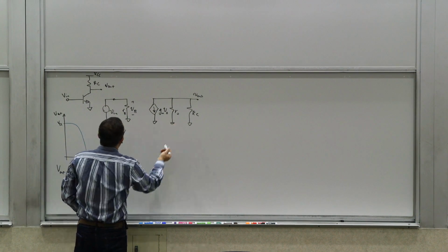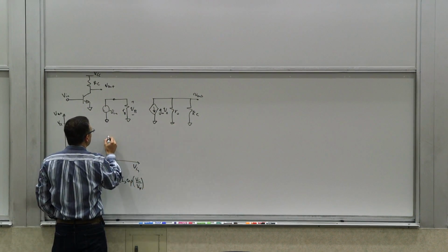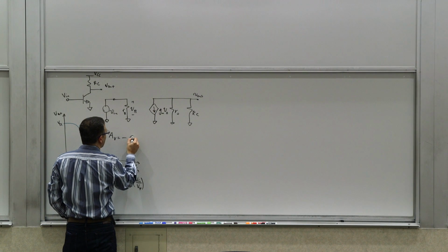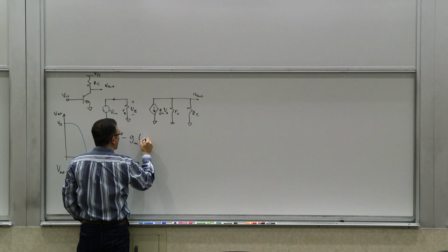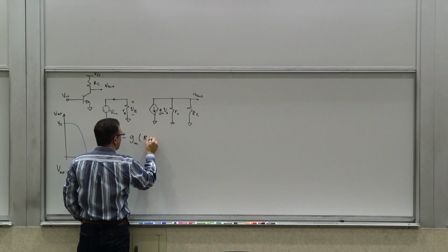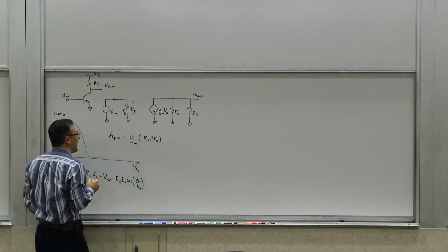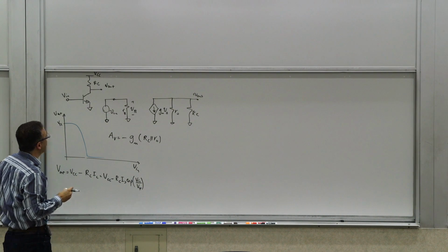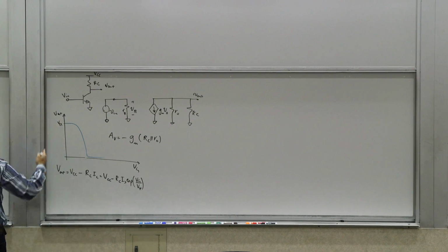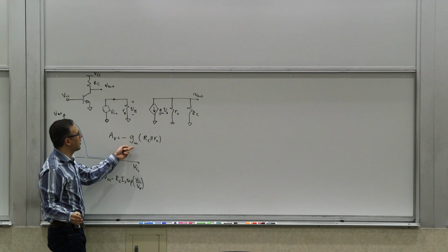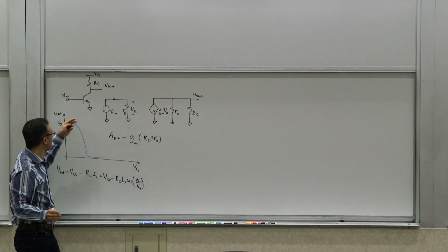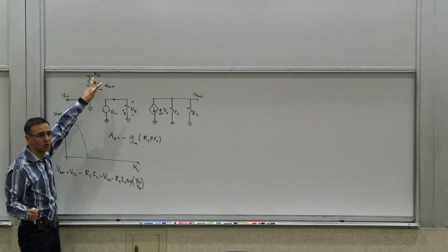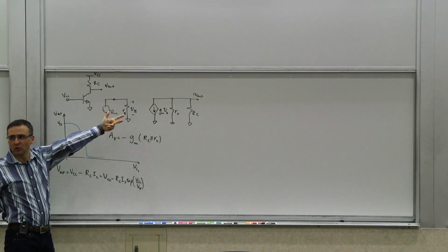So we had this, and then we calculated the gain. We demonstrated the small signal gain Av to be gm times RC parallel ro. And we saw that the maximum that you can get from this kind of stage was essentially gm ro, assuming that you present a very large resistance. We said that if you had an ideal current source here, it would become an open loop.